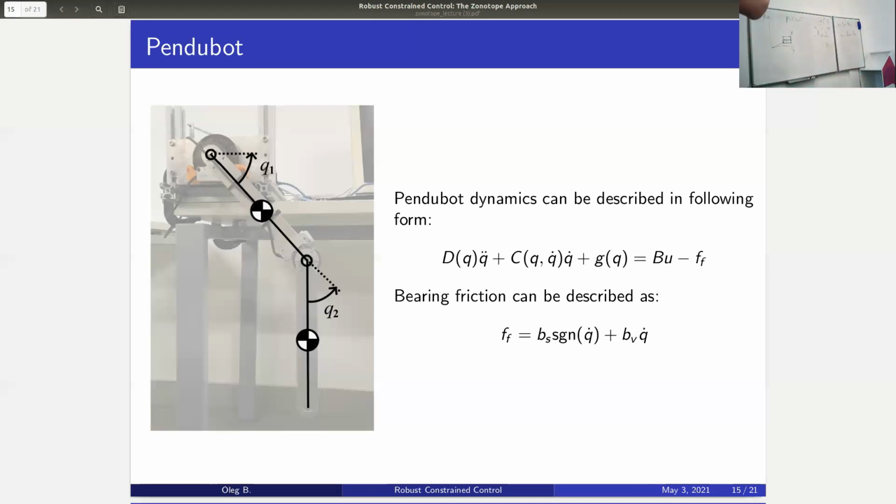for example, a robot, it's a strongly non-linear system, but you can linearize it. And when you want to make some movement for the robot, first you design your trajectory for the non-linear system. When you get the trajectory, you get T. You know how long your trajectory is in time. You know the discretization of your system, how often you make control actions, and you divide the time of your trajectory by dt, and you get the number of points.